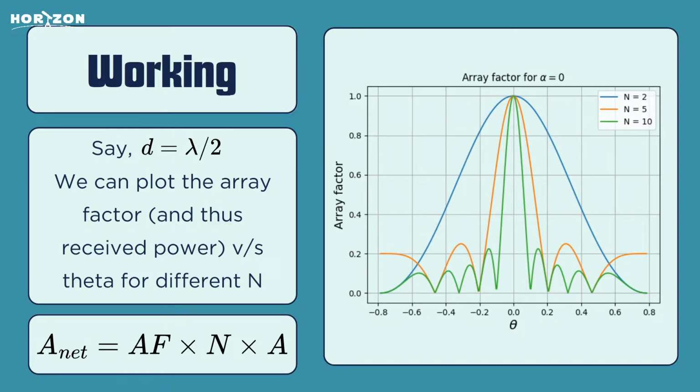One more thing we notice is that when we keep increasing the number n, which is the number of antennas in the array, the radiation pattern becomes narrower. So the whole concept of directivity becomes even stronger. There's only a very small theta range around 0 where my gain will be the highest, so I'll receive the maximum of my signal from that one small area only.